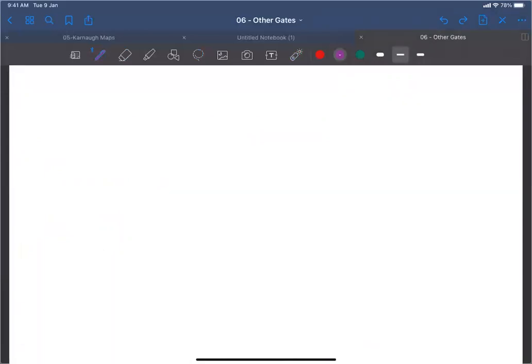Then what happens is that you need to select one of the 4 components. Selecting one of the 4 components means that you need 2 bits for the selection. So my enable will be 2 bits now, enable 1 and enable 0. It can be 0 0, 0 1, 1 0, and 1 1. Then the output Y will be X0 if we have 0 0, and X1 if we have 0 1, X2, and X3.